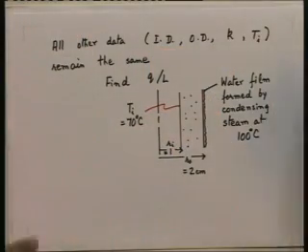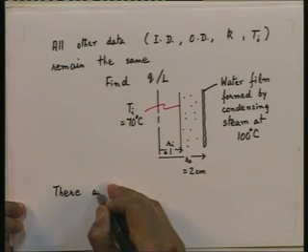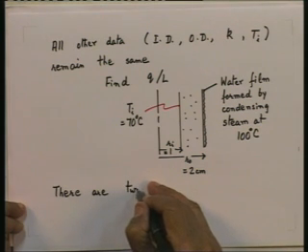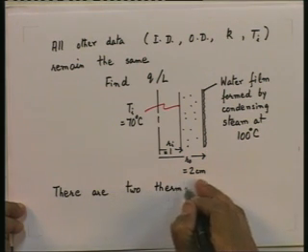Now, what is the change compared to earlier? Earlier, from Ti to To, that is from 70 to 100, there was only one thermal resistance, and that was the thermal resistance of the tube. Now, we have two thermal resistances in the path of the heat flow when it is flowing between the temperature difference, 70 from inside to 100 on the outside.